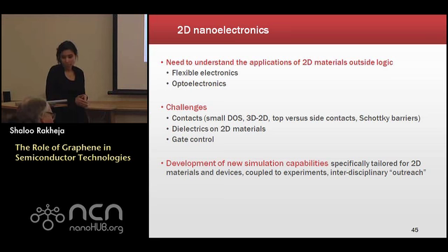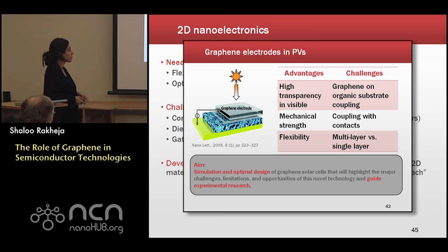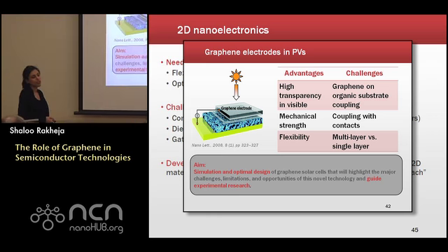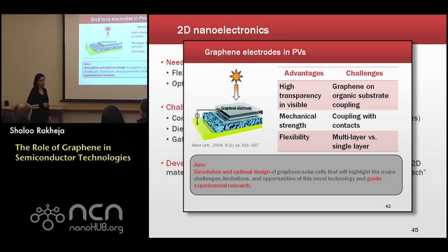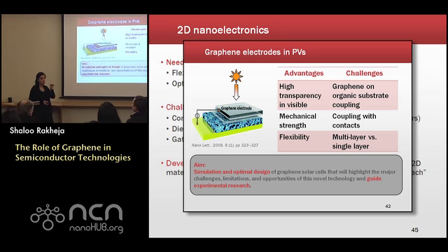Can you go back to that? Yeah, sure. Because I think, okay, so you wrote that zeta equals 30%. Oh, that I was just doing for one simulation. I just wanted to show you one particular simulation of what a quasi-ballistic charge model would do and what a drift-diffusive charge model would do, and that was only for one channel length device.